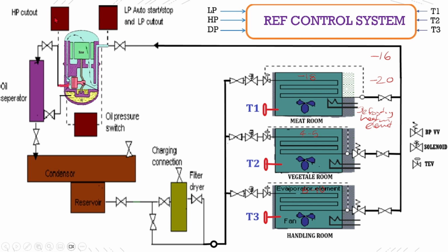You have to go there and visually check the plant or the system, because high pressure cannot be acceptable. So the operator must physically visit the plant and observe if there is anything wrong to cause this alarm. Maybe insufficient cooling of air in the condenser, or any moisture ingress, any air ingress, or some other reason, maybe malfunction of the HP cutout or whatever. First you have to identify the actual cause which triggered this HP cutout, and before resetting it manually, you must solve the problem. Only then should you reset it.